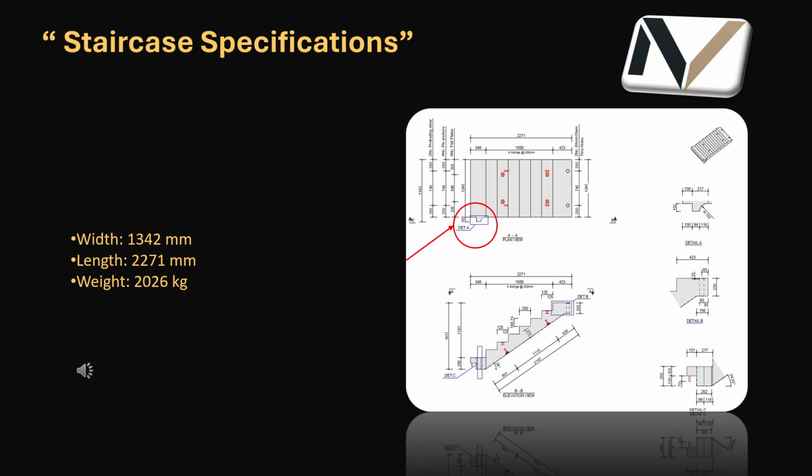We should be really careful about the length of it, the height of it, and where it is exactly positioned, as it needs to seat exactly on the landing that it was designed for, and all of these issues should be checked. But apart from all of them, the arc which has been designed and shown on detail A on this DWG should be cast properly and intricately.